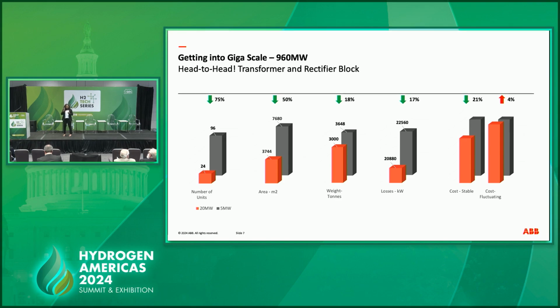And keeping aside the IGBT, keeping aside the thyristor topic, if I'm talking about just the grid feeding the plant, I do need a grid short circuit ratio of 2 or 3. If not, your plant is going to have operation problems and stability issues. It doesn't matter if you're an IGBT or a thyristor.